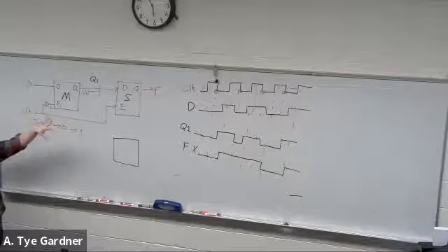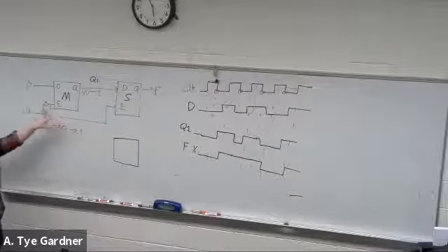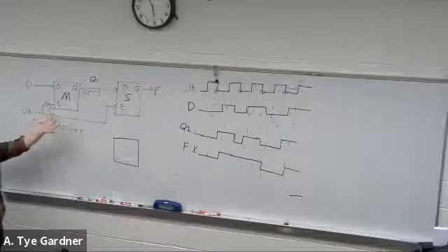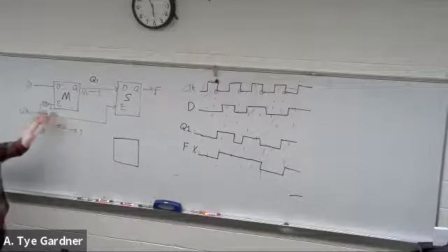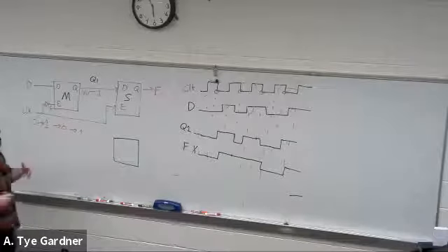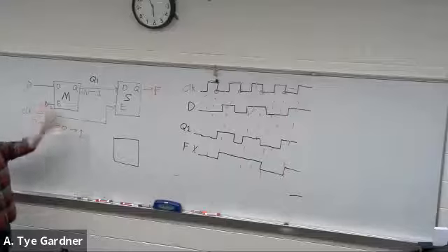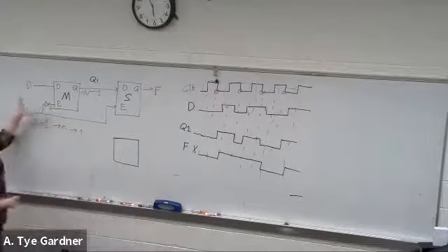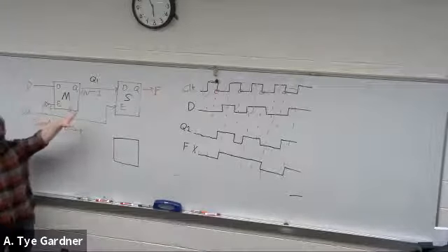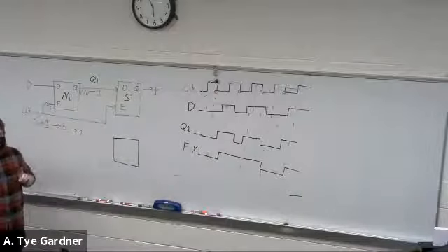This master-slave notation is really prolific in industry, and they're doing a pretty active job of moving away from that notation. In 3610 it comes up more, and we'll talk more about what it's moving towards. I just don't know because we don't do a lot of design with this low-level stuff. But just so you know, you'll see that in industry for decades to come, because of legacy stuff. So this configuration has taken 2D latches and turned them into a 1D flip-flop.